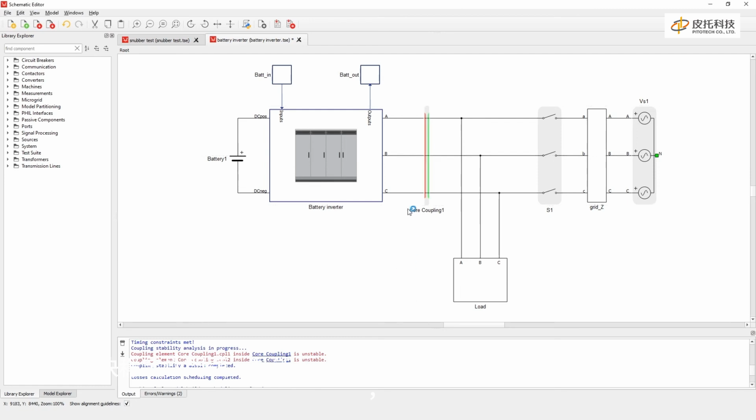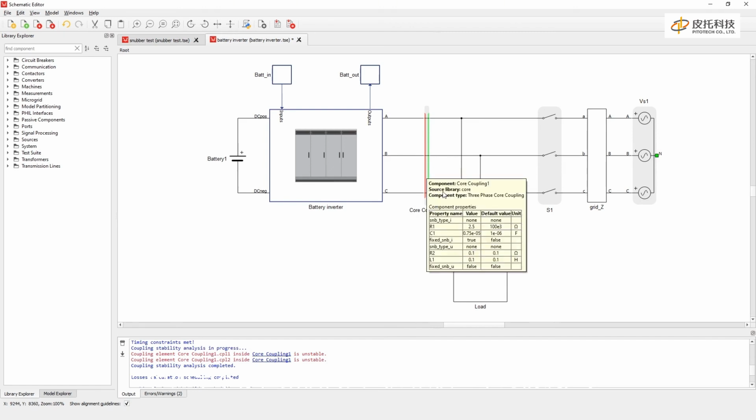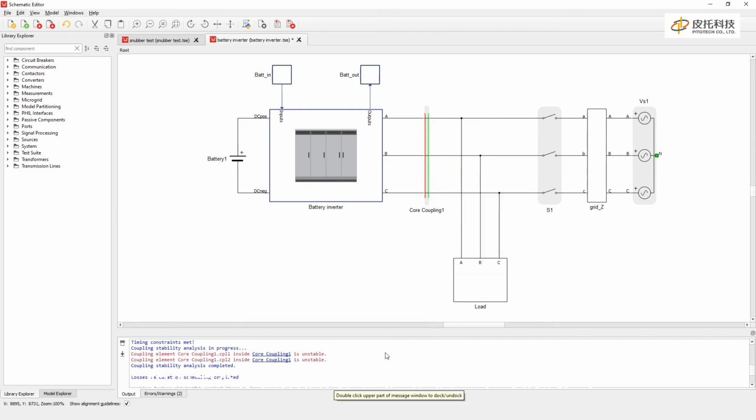Dynamic snubbers can be used to solve topological conflicts, but if a topological conflict is not present, as is the case in this model, enabling dynamic snubbers will do nothing. Because of that, we need a fixed snubber to improve stability.